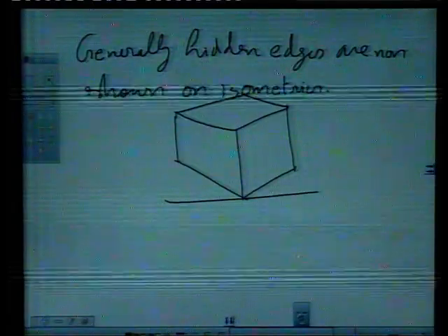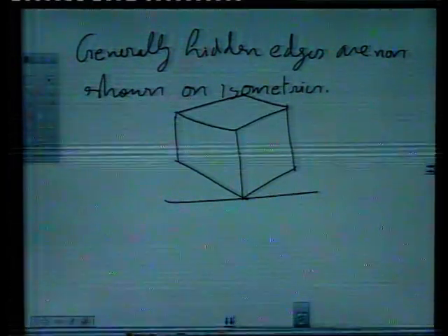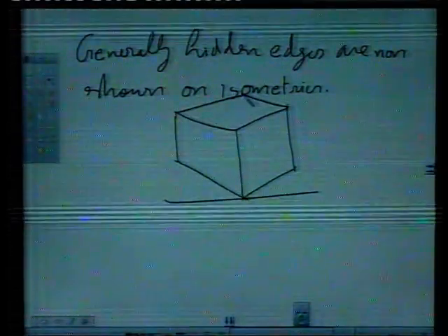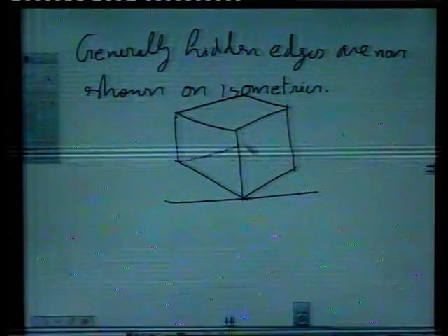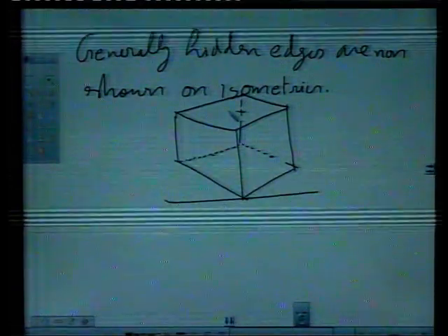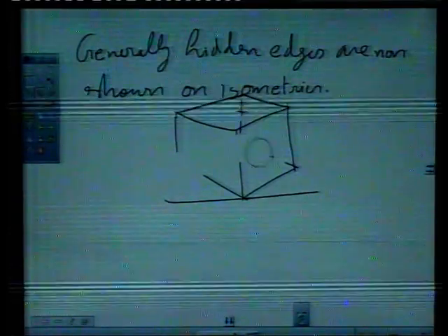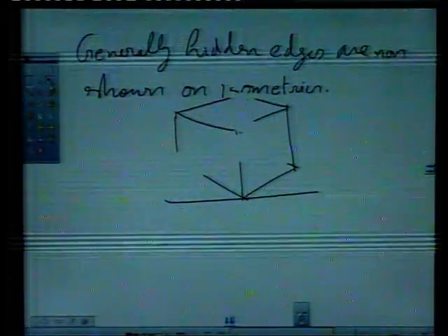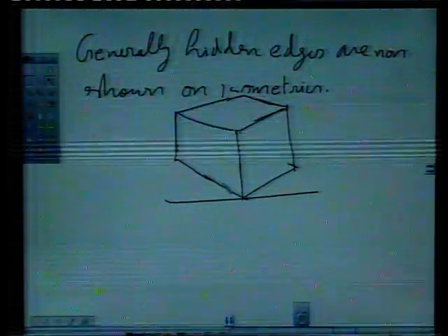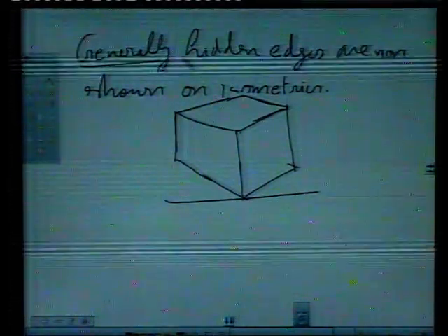So, all the axes or edges which are not visible, we have not shown or we should not show. Otherwise, these 3 dotted lines represent the hidden edges. Okay, we need not show hidden edges. Simple point, I think it is clear to you. Hidden lines are generally not shown on isometric drawings, we can show them if we need.